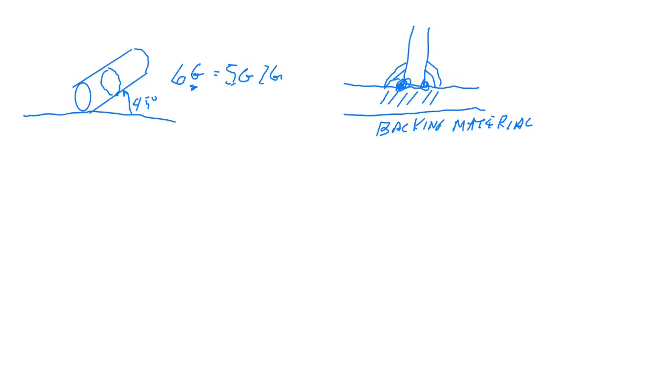Well, these G welds here are hard to do because I'm going to prepare my pipe. Remember, I want to weld it on pipe because it qualifies me for plate. And then I'm going to weld to what's called an open root, which is hard. It's hard to do this, but this is what pressure welders weld to. They weld to an open root. They don't test with backing material. And if I can lay down a good root pass,